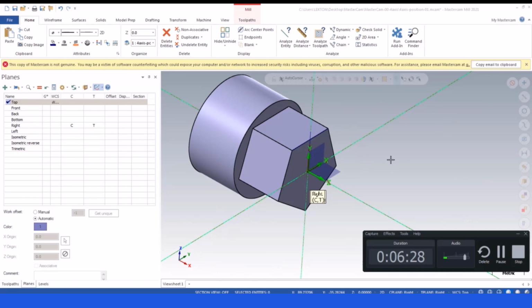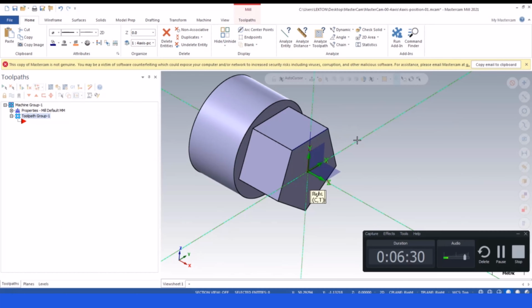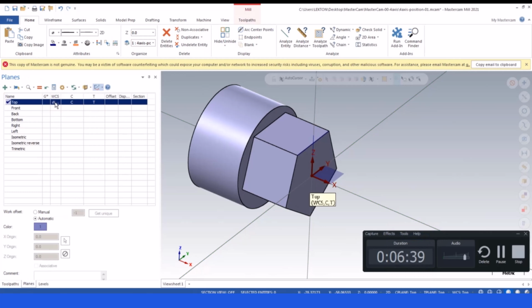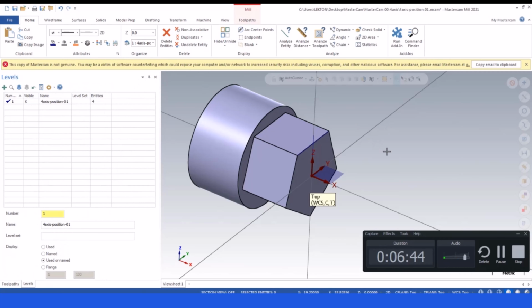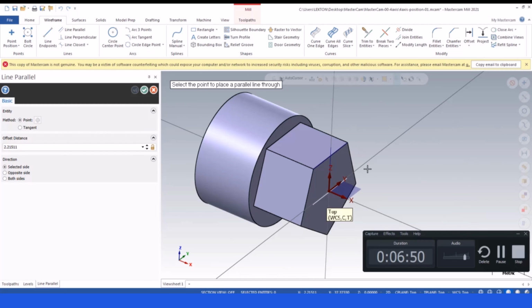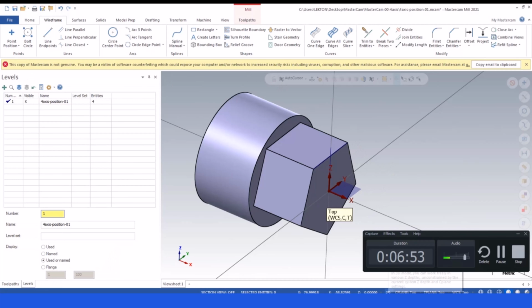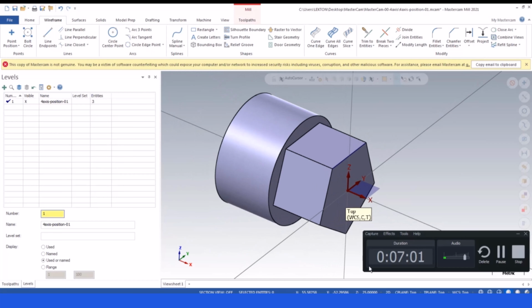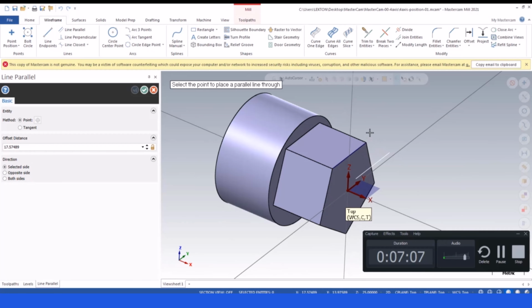So at that point, we're going to create our toolpath. That's why maybe we should turn to C-plane top. We can also use the plane options, VCS on top, C-plane, and tool plane also on the top view. Then I can use wireframe and parallel line options here. I can select here. Of course, with my 2D options, my Z position must be on that line. Okay, we can also delete that one. This is 25 Z position, so I can use parallel line options here.